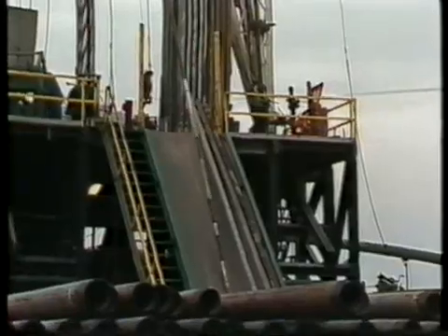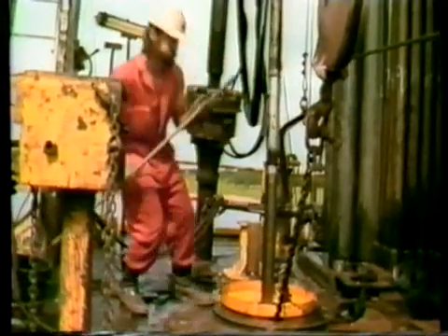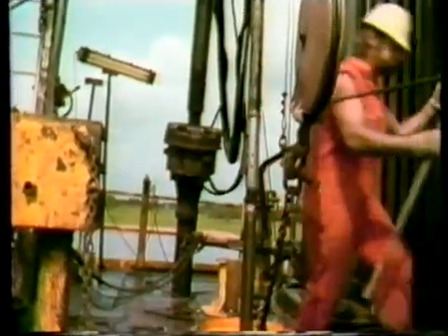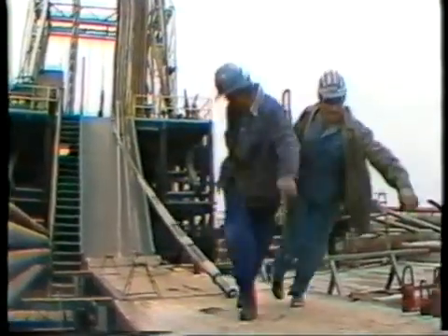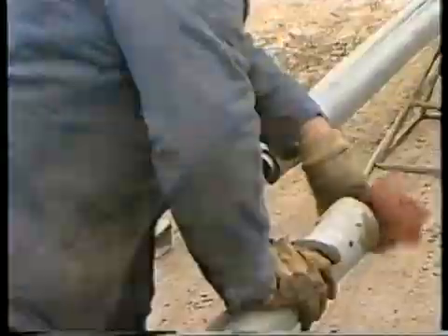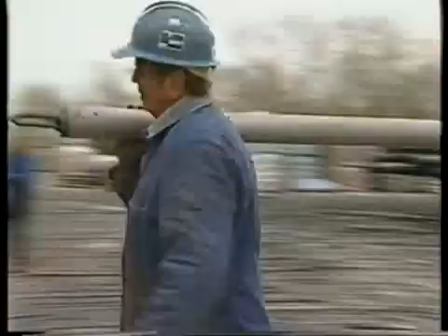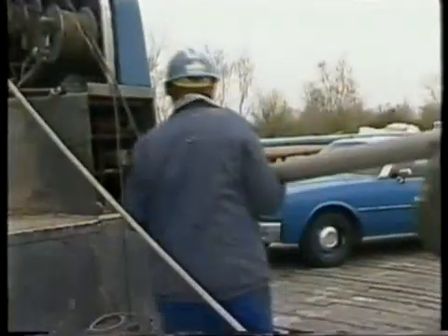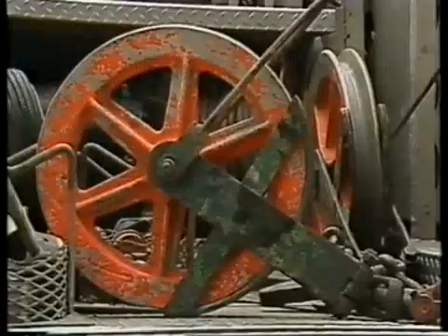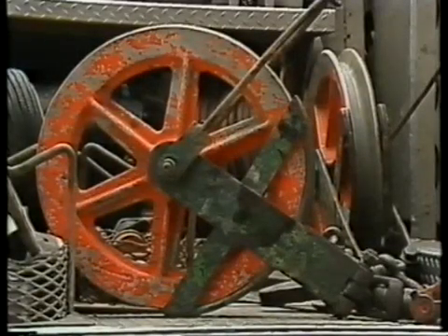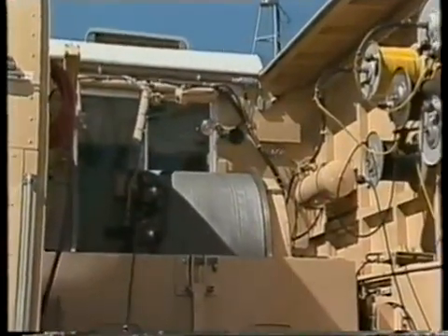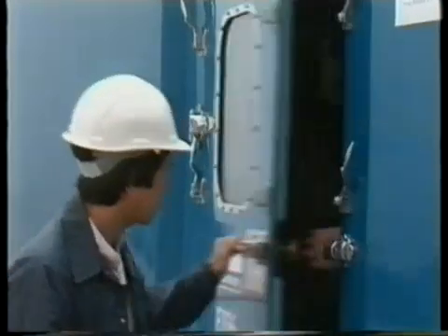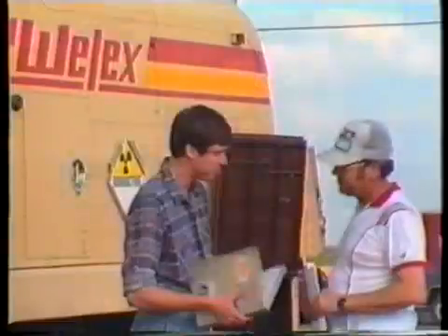Upon completion of the last logging or sampling run, rigging down proceeds in a manner similar to the reverse of rigging up. Any radioactive sources are removed from their devices. Logging tools are lowered back onto the catwalk, cleaned up, broken down, and racked for transportation back to the field office. Shiv wheels and accessory items are detached and stored in the truck, and the cable system is secured. Field prints are made for the oil company representative.